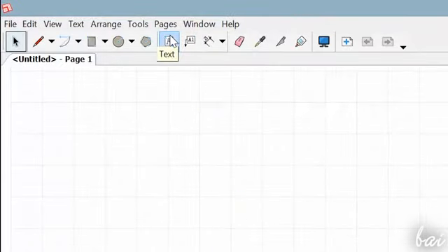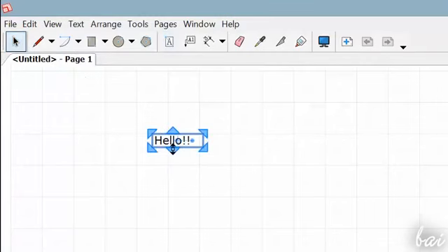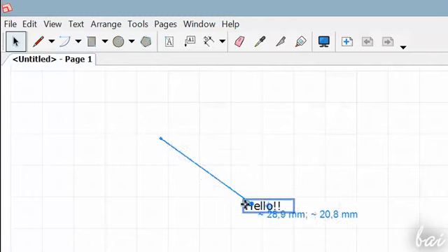You can also add text to your 2D project. Just go to the Text tool and then click on a point to start typing. When you finish, click elsewhere with your pointer. Pieces of text are included inside the text box, which is highlighted in blue, and can be moved dragging it as seen before, using the Select tool.